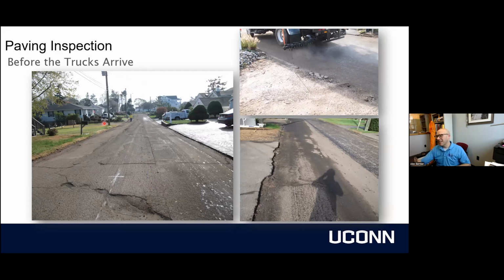The reason this is such a concern is even if you pave over this with a paver and make it smooth and black on day one, there's going to be stress concentrations, meaning as a truck goes over this portion of the road, it's going to hurt the road more in the shallowest parts, and there'll be this big transition there and quickly create cracks in the surface.